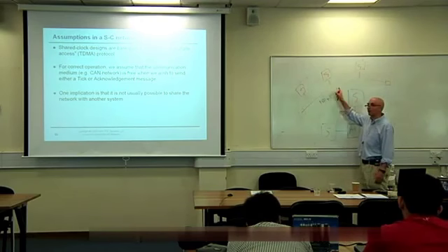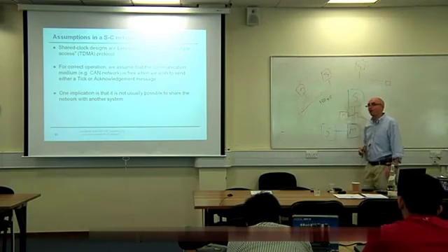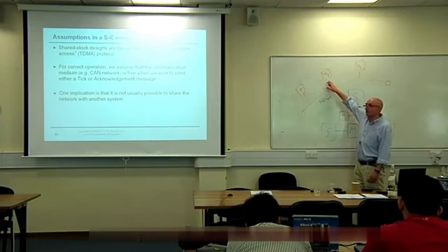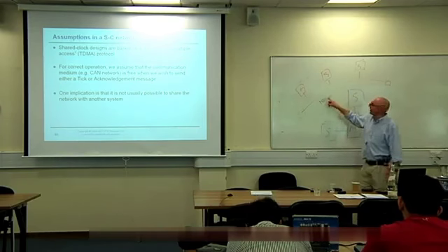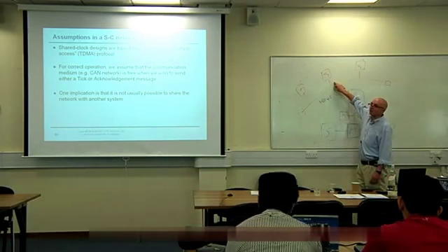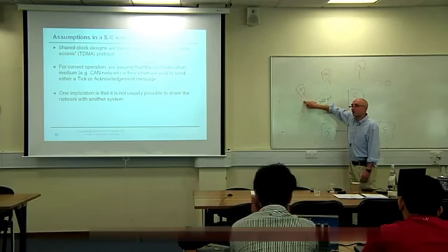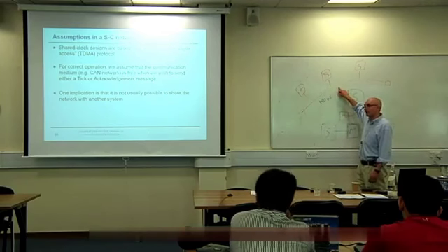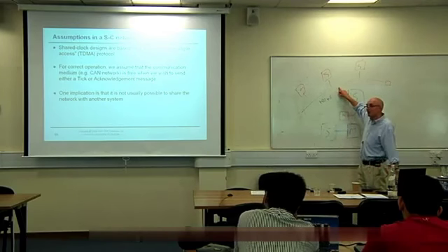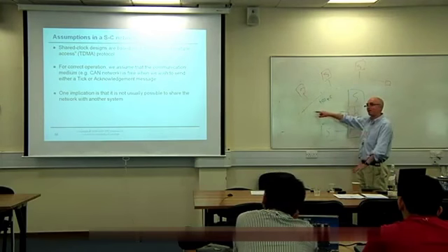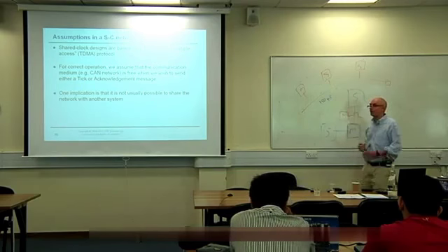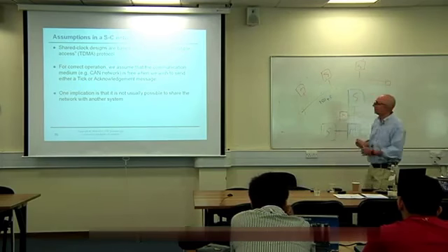I mean, apart from anything else, suppose you don't worry about that. Suppose you say, okay, that's not my problem. I'm just going to focus on this node, and the guys in the corridor down the road can worry about that one. How do you know then that your task 31 in here, which needs the data from here, is actually going to have the data it needs by the time it's scheduled to run? You can't otherwise. That message might be somewhere in the message stack waiting to be sent, unless you have control over these things, because there's not usually much space for error.